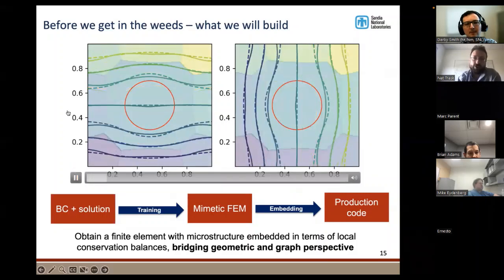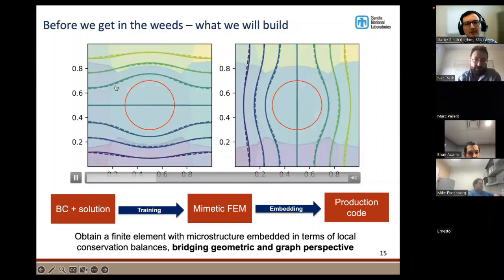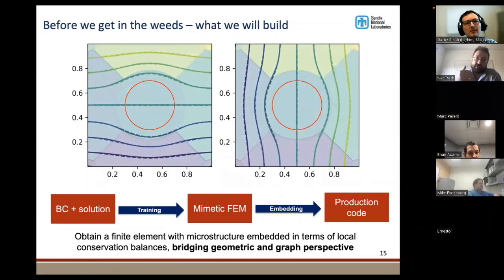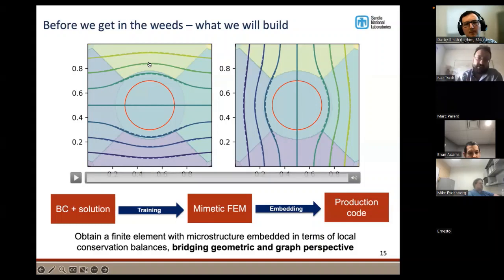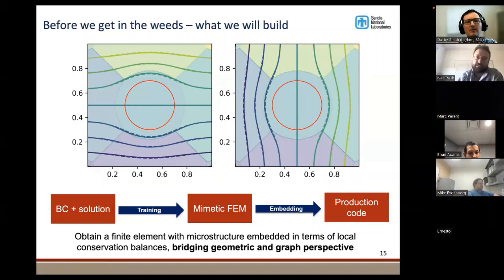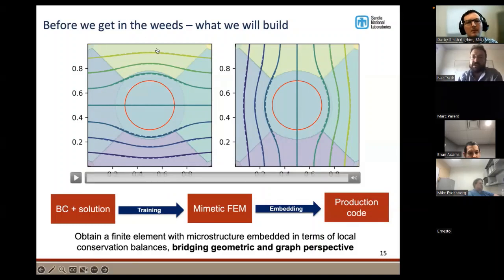And so when you train, what you can see is that we're asking for control volumes. That's these polygonal-ish looking subdomains in the back. We ask for subdomains such that an integral conservation balance holds over each one of those domains exactly. So we don't know what the fluxes are. We're going to discover what the fluxes are. And so what this is doing is, like cats in classification, you say this part of space is the cats, this part of space is the dogs. You're taking these same kind of classification architectures, but you're using them in order to partition up the space.